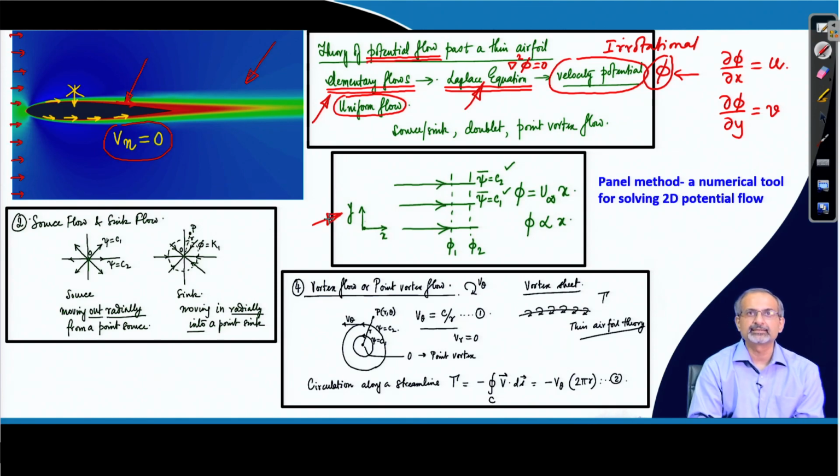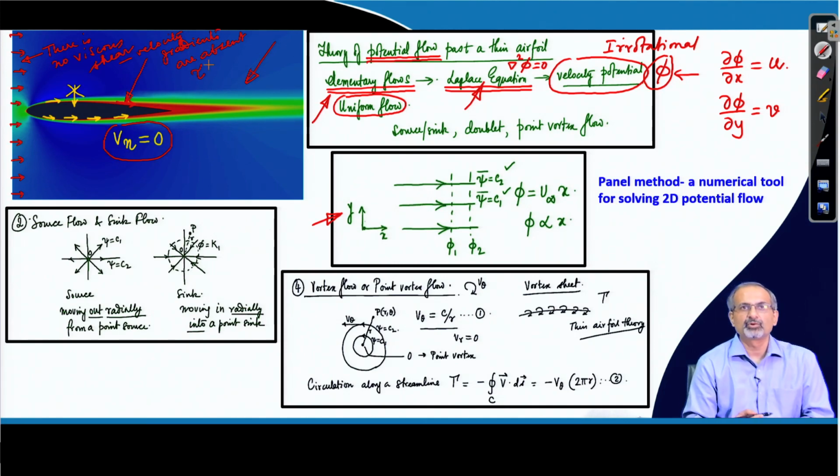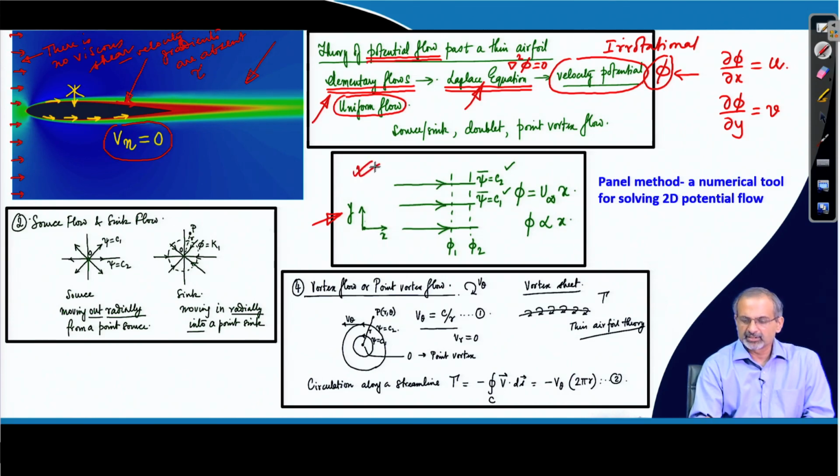The only thing that we are saying is that in such a region there is no viscous shear. That means velocity gradients are absent, and therefore, what is the consequence? Tau will be absent, because tau xy is dependent on del u del y, del v del x and so on. So, here tau would be 0. So, it can exist in potential flow, it can as well exist in viscous flow.